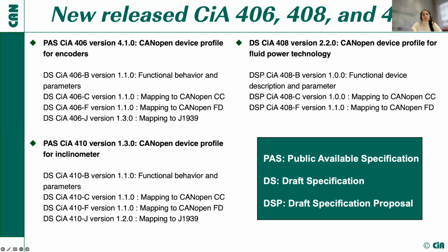It also provides the operating principles of the encoders and specifies encoder output process values such as position, speed, acceleration, and jerk. And also it specifies the CANopen safety parameters such as safety position and safety speed for encoders with CANopen safety functionality.